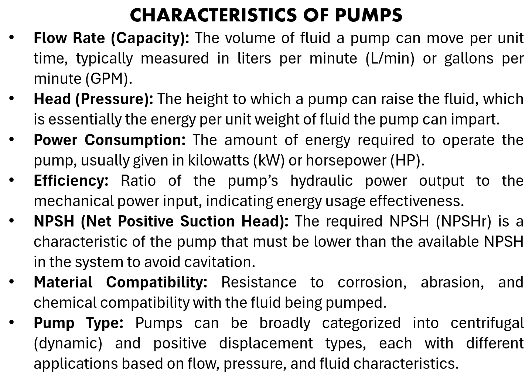Then the efficiency of the pump and net positive suction head, and we have already seen head pressure. Then material compatibility: corrosion, abrasion, and chemical compatibility. The fluid being pumped should not affect the efficiency or the mechanical properties of the pump. That is material compatibility. And then the pump type, which we can choose based upon our requirements. There are different types of pumps, as we have seen in earlier slides.